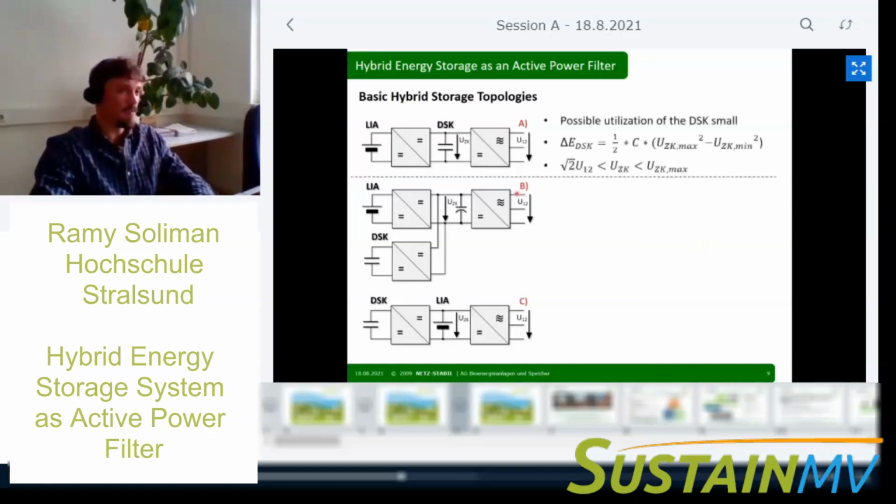First of all, we start at the front end, and here we are connected to the power grid via a converter, which converts the three-phase voltage from the grid to DC voltage and vice versa. We need DC voltage to store energy in our supercapacitors or in our batteries. So this basically connects our whole system to the grid, and it's the so-called grid converter.